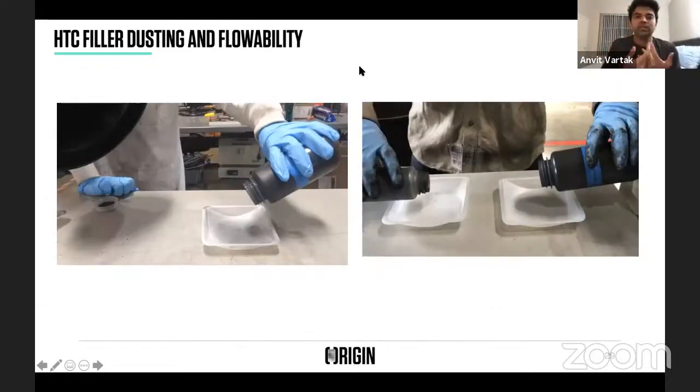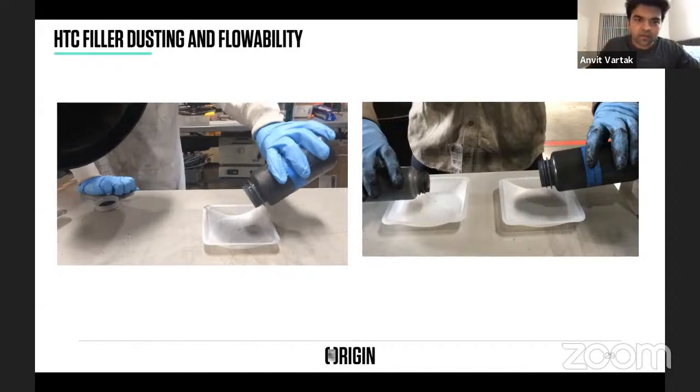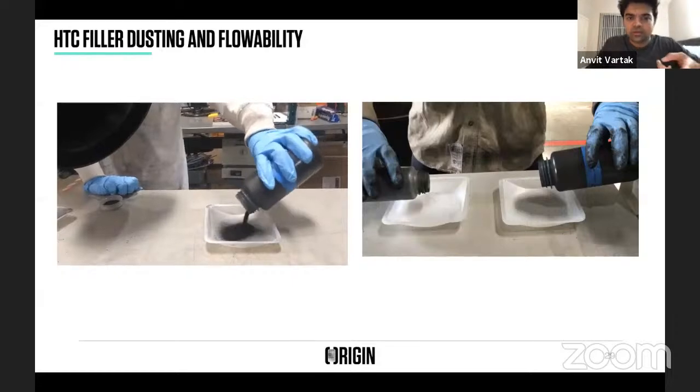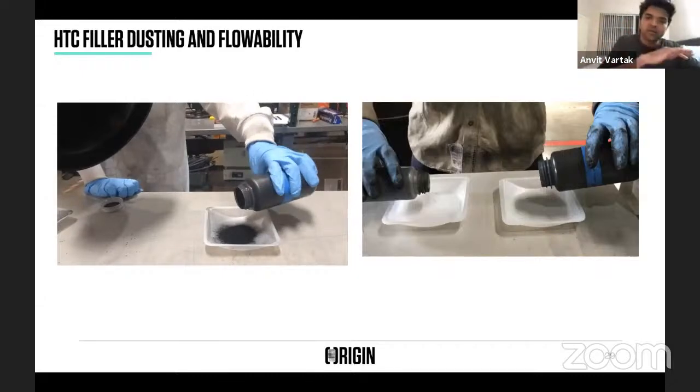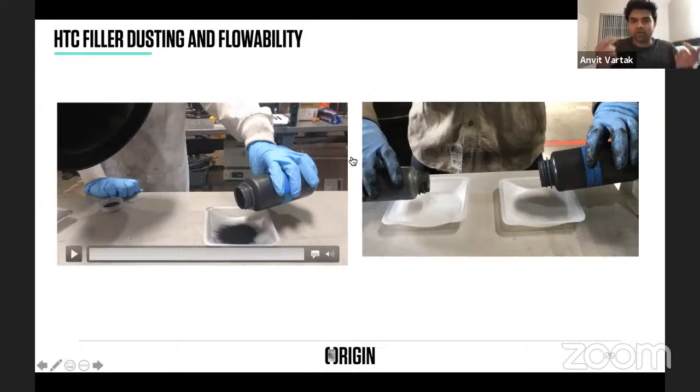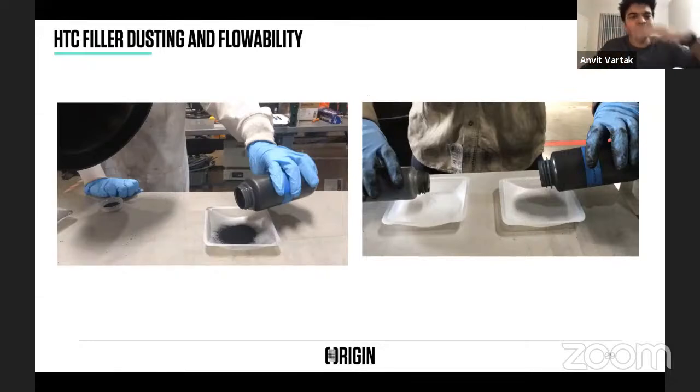We have everything that we need in terms of physical and chemical properties now, but we faced a huge issue wherein our material was not getting added properly into the rubber, and getting mixed, because you can see how it struggles to flow out of the jar. So imagine having a conveyor belt, making it flow and dropping it down. It's going to rise up as a very light powder and create a dust, and you will lose more than 50% of your material, and it won't get added to the rubber that you intend and process properly. So very weak reinforcement, and you lose a lot of material.